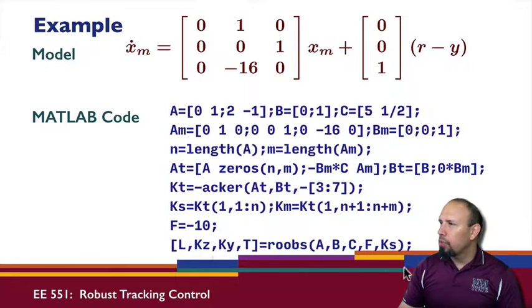Now, in my reduced order observer, I'm going to choose F to be this, because my plant itself only has 2 poles. And so as a reduced order observer then, I'm already, in a sense, measuring one state. And so I only need to observe the other state.